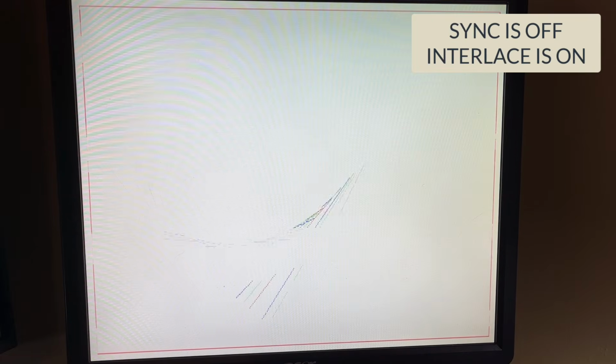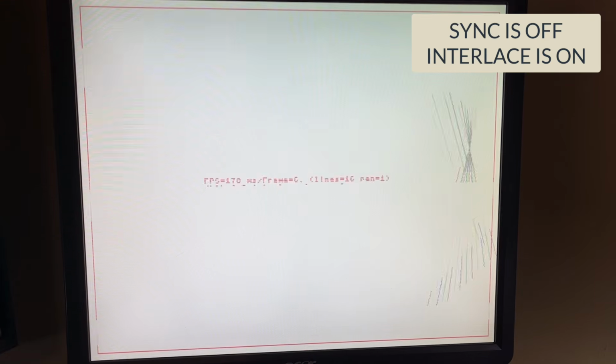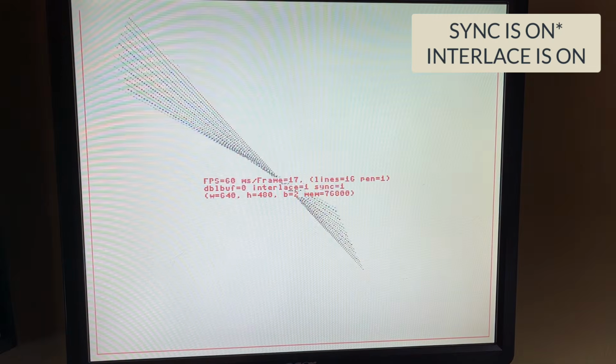Okay, so we're now at 640 by 480 by 2 pixels. As you can see, the display is now working. We're not seeing any more of the blue and black boxes at the bottom, but the display is not coherent, right? We're drawing over the frame buffer at the same time as we're displaying it. So I'm going to turn on synchronization to see if we can fix that. And now we have a stable display.